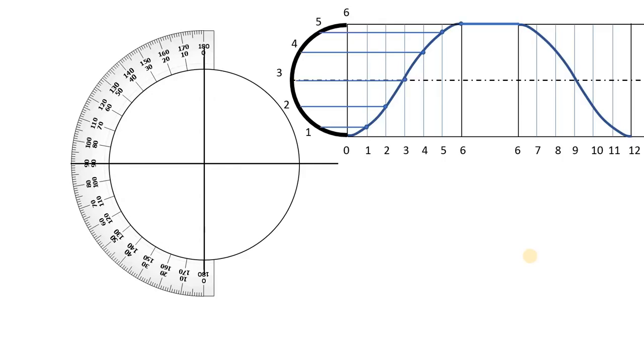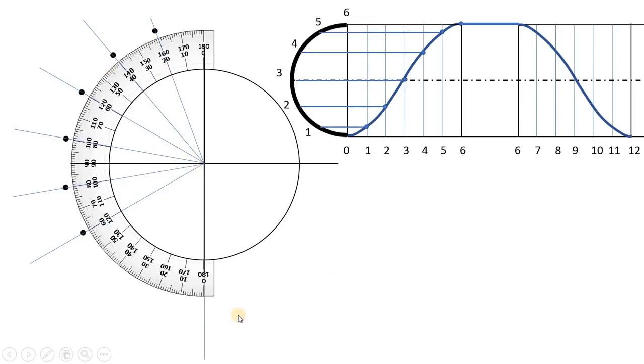Now we'll draw the cam base circle of 5 centimeter radius, and then we'll divide, taking this particular vertical line as a reference, the given base circle in 6 equal parts of 20 degrees for our outstroke, because our outstroke is of 120 degrees. So 120 divided by 6 is 20 degrees. So these are the lines which we have drawn at 20 degrees from the center of this circle. Then the remaining 60 degrees is for dwell.